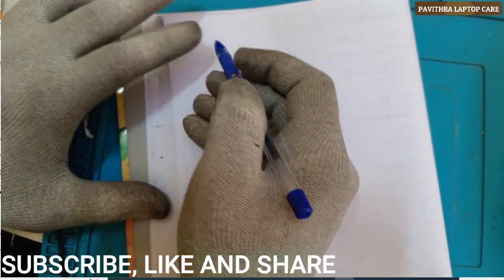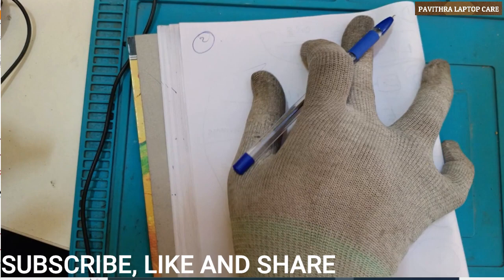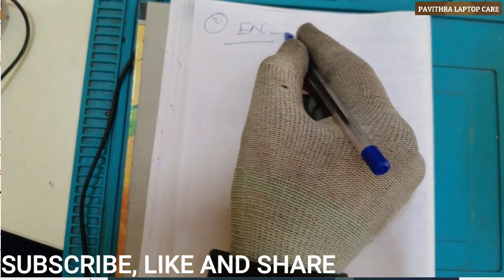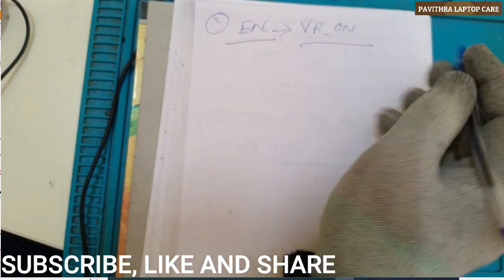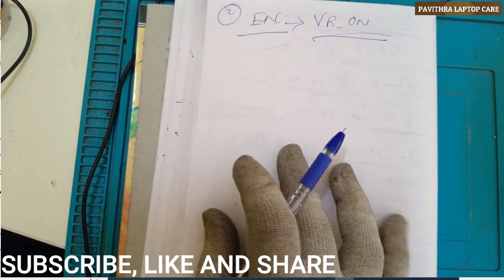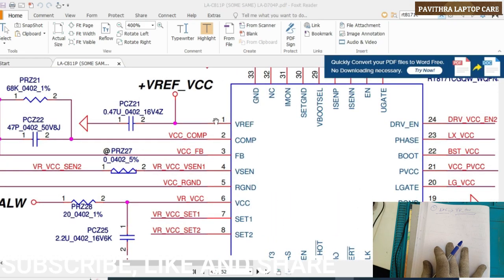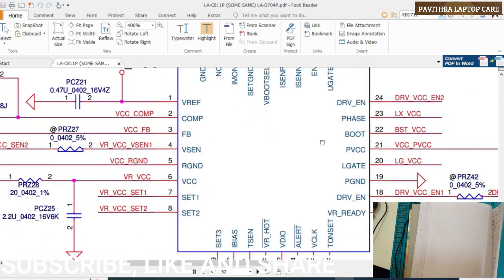Now it's the second point. Second one, which one? Enable. At that time I told you enable is nothing but the VR_on signal. This is a common name. But in this particular IC, will you check where it is? Search VR on, where it is?